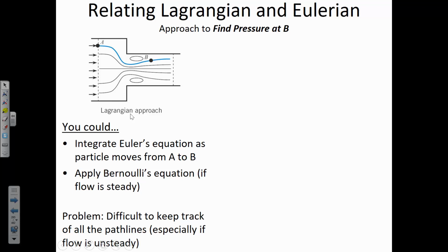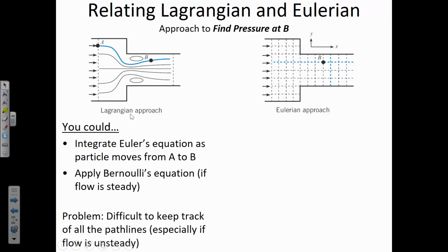And so a simpler method for finding out how pressure might change through a flow field like this is to divide the flow field up into elements. Now, we've just been talking about the Reynolds transport theorem, and the idea there is that there are some control surfaces that fluids flow through, and inside of the control surfaces are control volumes. And so when we develop a mesh through a network, and that's what's being illustrated here, you can think of each one of these flow elements as a control volume.